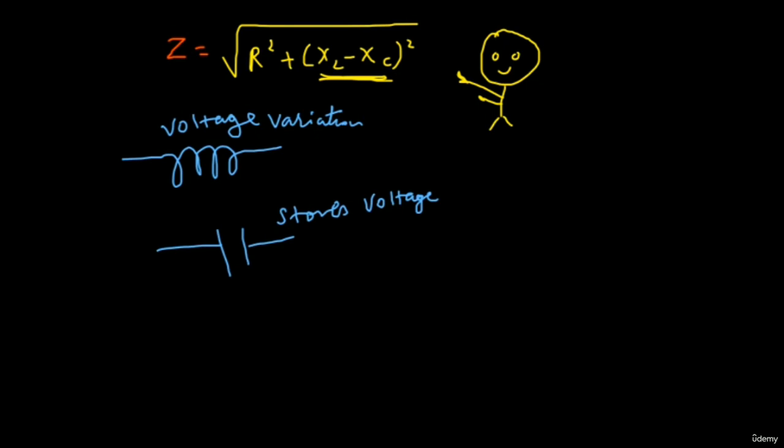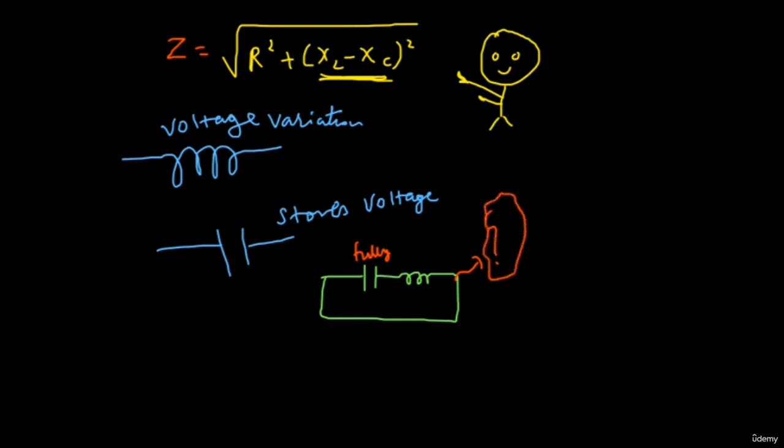Now listen to this part very carefully. If I place a capacitor and an inductor together, no power source, nothing, and somehow I charge the capacitor fully. So this is zero charged, or not fully charged at least. What is going to happen after some time? What do you think? Well, that's the pondering question. Yes, the capacitor is going to get empty and the inductor is going to get charged up.